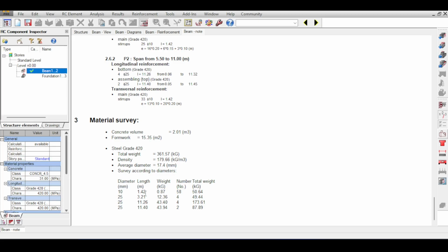Now, depending on the country where you're working, in some countries every centimeter is perfectly fine. Like, you can ask a steel manufacturer to provide you with a steel bar of 1.333 meters if you want. Now, this is in some countries. I don't know. In the countries where I worked, usually steel is cut into lengths that make sense, like 1 meter, 1.5, 2 meter, 3 meter, 4 meter. And the criteria here is that you cut your steel bar into lengths that are able to be divided.